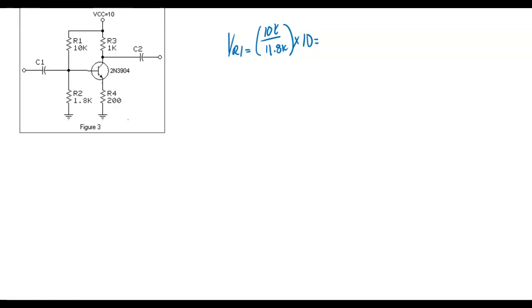We're calculating VR1. You're talking about VR2, but we're calculating VR1, Kelly. Because y'all got to calculate all the voltage drops across all the resistors, right? It doesn't make any difference which order you do it, and we have several laws. So 10K, which would be the size of this resistor, over RT times this voltage, and what do we get? 8.5.